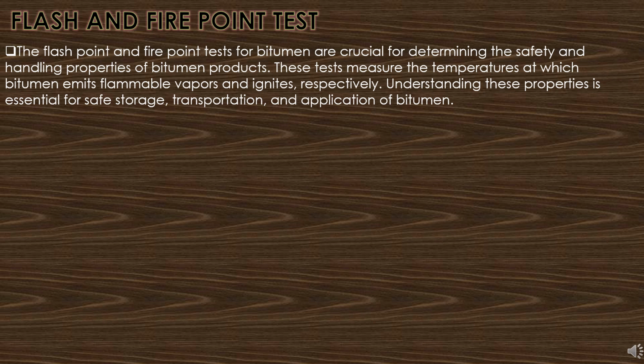Our next test is the flash and fire point test. The flash and fire point tests for the bitumen are crucial for determining the safety and handling properties of the bitumen product. This test measures the temperature at which the bitumen emits flammable vapors and ignites, respectively. Understanding these properties is essential for safety, storage, transport, and application of the bitumen.